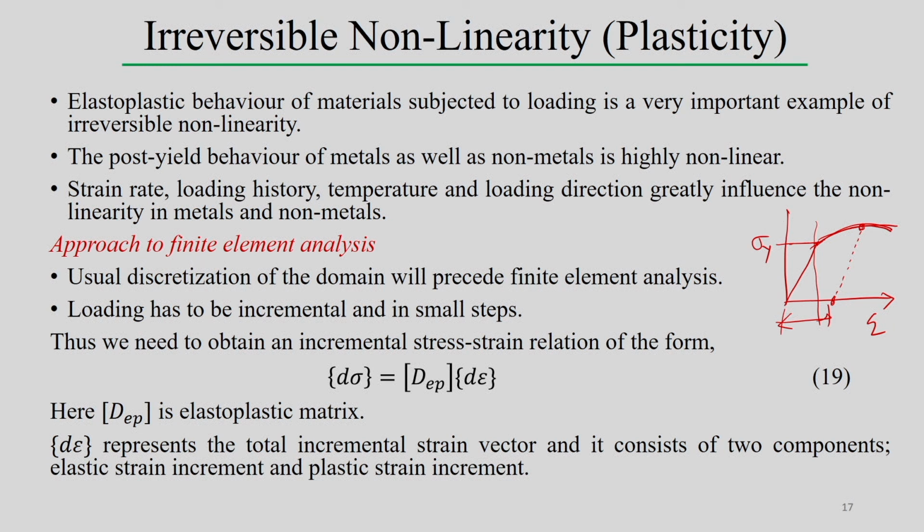Now we will try to understand how this incremental mode stress analysis can be done using the finite element method. Therefore, loading has to be incremental and in small steps. It is not possible to analyze in a single step to reach a particular point; rather, in the plastic domain we can reach it through small increments.